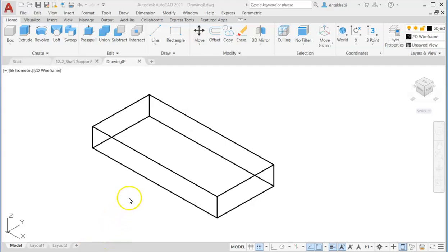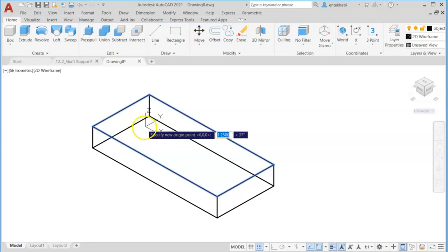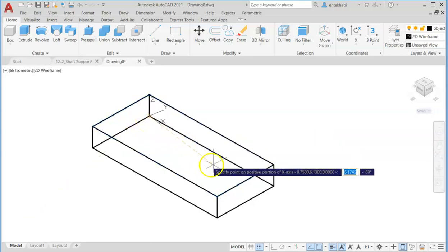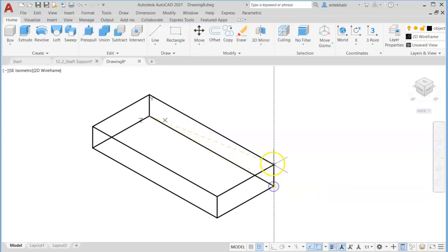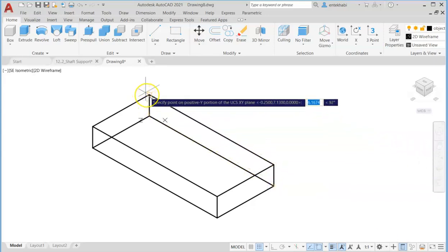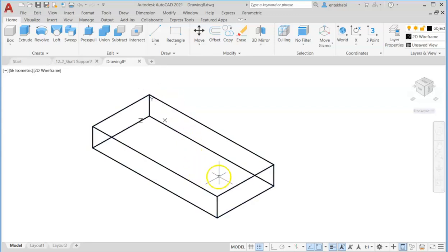Okay, now we are going to change our UCS 3 points. And selecting the 3 points option, we pick the origin to be on this corner here. And x-axis would be other corner by selecting endpoint. And selecting another endpoint for y-axis. We select those points where XY switches parallel to the screen.